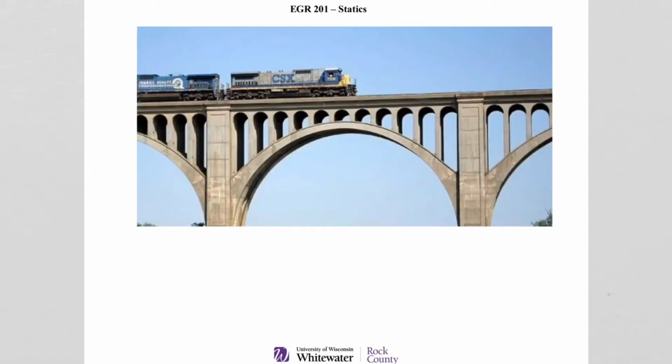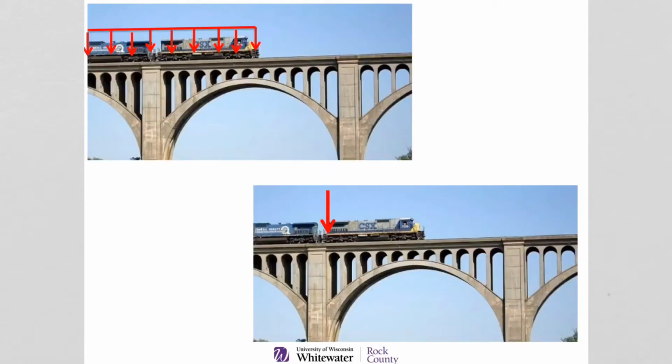I know I've shown you this train before, but it's a great example because we deal a lot with these things in bridges and in beams. So this force that we're looking at again of this train is a distributed force. It has some loading along the x-axis, if we created this as an x-axis, right? And this would be our y-axis in this direction. But there's some loading that goes along with it, and we can then create a similar system, an equivalent force system, which is just a single force. And then we can really analyze it looking at it from a statics point of view.